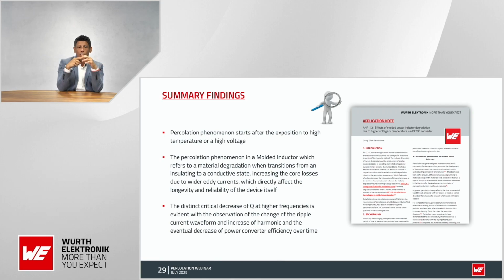We're speaking about new technologies on molded inductors like co-sinter, transfer technology, hot molding, but everything is related, because at the end we have a coating layer, we have some glue in between, we are using organic combined with non-organics, and to guarantee the soft saturation, but on the other hand, we can suffer percolation.